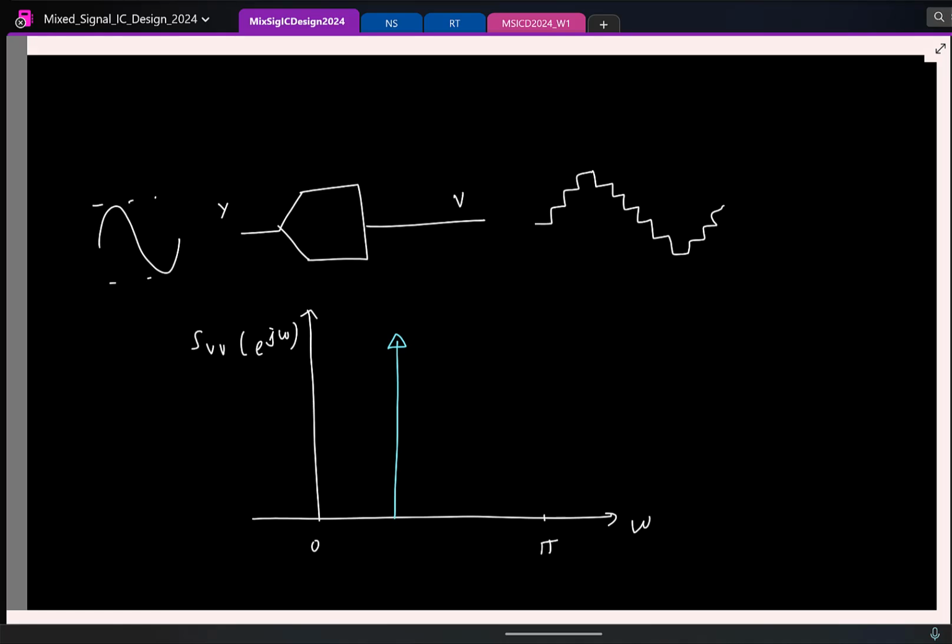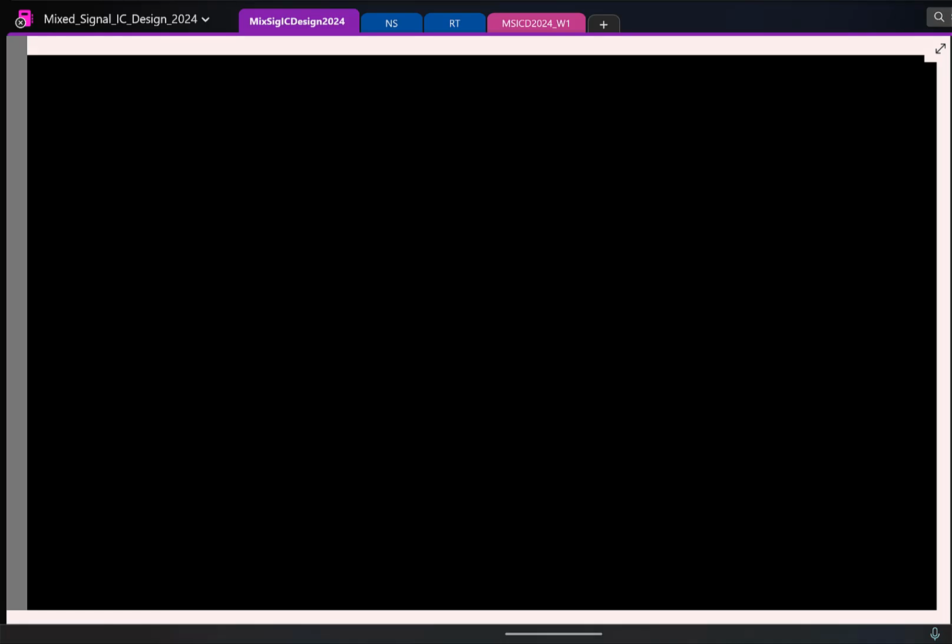Now, you tell me, for the quantization noise, to find its probability density function, did we do any analysis or what did we do? For making a statement about the PDF of the quantization noise, what did we do? We just made an assumption. So here also we need information about its PSD. What do you think we can do? Assume. And what is the simplest shape you think you can assume for the spectrum? Okay, flat, that's what you mean, right? Yeah, so that is a different name. So that's what we'll do.